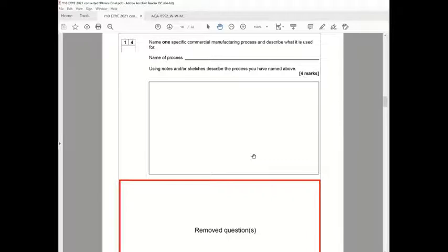Right, there's a little bit of confusion here about what exactly is a manufacturing process. Now, I've had a conversation with different people about this, and manufacturing is sort of adding, taking away, altering the form, altering the shape. For example, vac forming. You've got a piece of sheet plastic and you suck it over a mold and you alter the shape. For example, injection molding, where you're injecting molten plastic into a mold, waiting for it to cool, and then out comes, you know, a little toy figure or something.